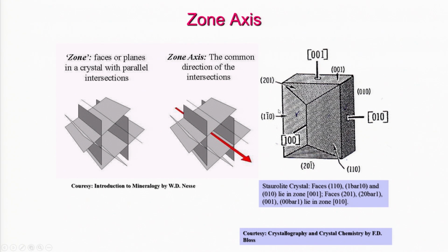I can give you a further example with this crystal here. Let us consider this crystal face here. This crystal face has a Miller index symbol of 1 1 0. So, this is your A crystallographic axis, this is your B crystallographic axis, and this is your C crystallographic axis here. And when we write 1 1 0, it means that it is parallel to the C crystallographic axis, and it intersects the A and B directions at unit cell lengths here.